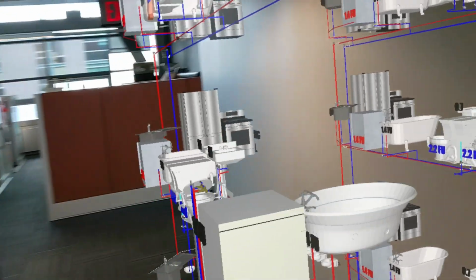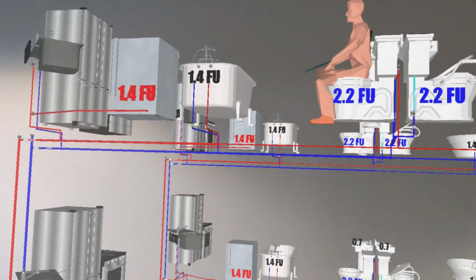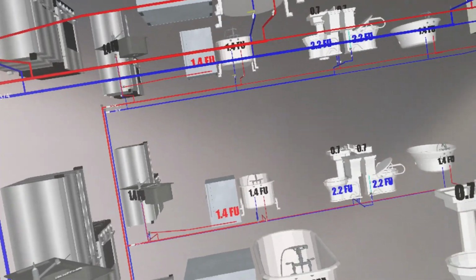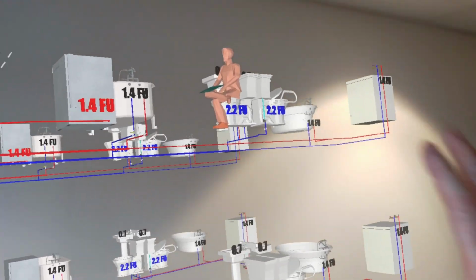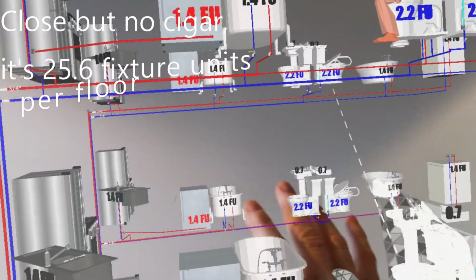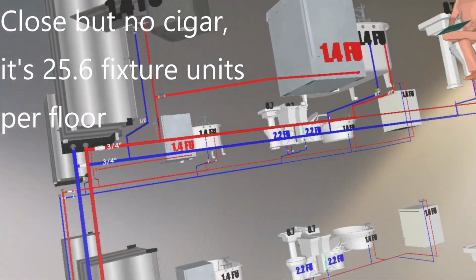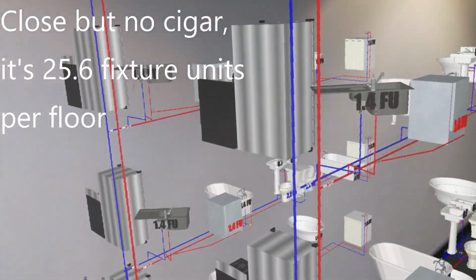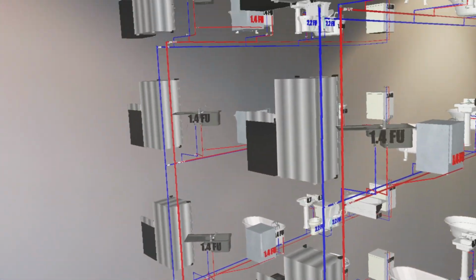Now, in order to figure out the fixture unit load, you have to know the fixture units of each plumbing fixture, which we find in the 2020 National Plumbing Code under 2632A, and it'll tell you all the different fixture unit loads. Now, these are all private apartments, hence all these fixtures would be under the private totals. So you'd have to count up all these fixture units. I think there's 26.5 or something per floor, somewhere around there, if I remember correctly. So then you just have to multiply that times 4. I think it's about 104 fixture units, somewhere around there.